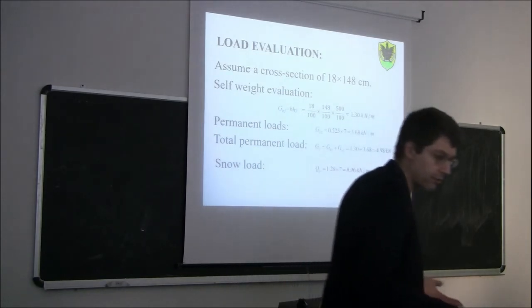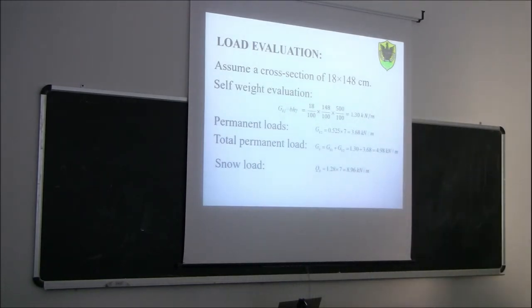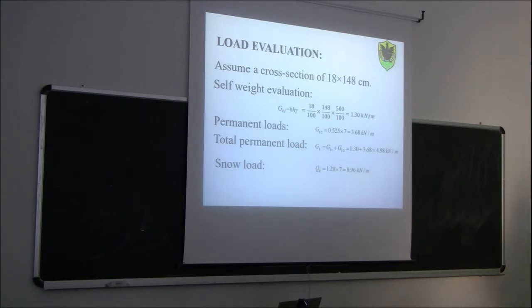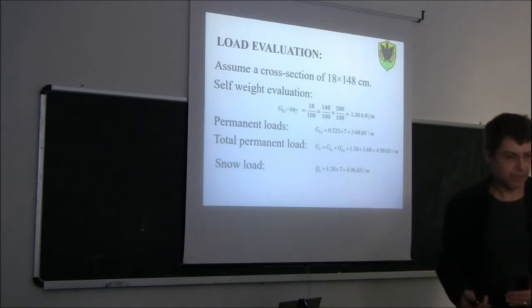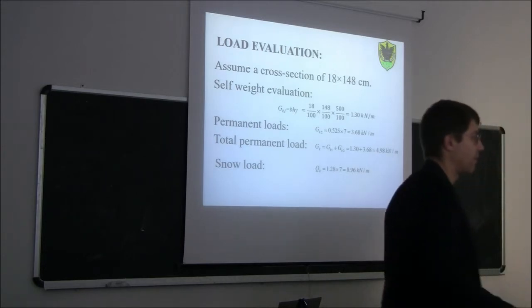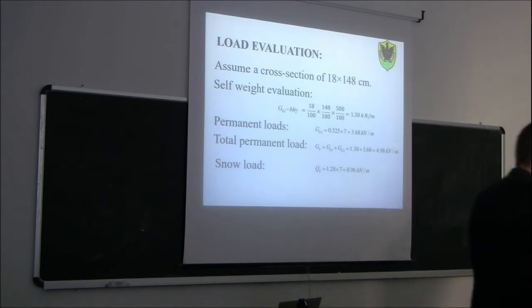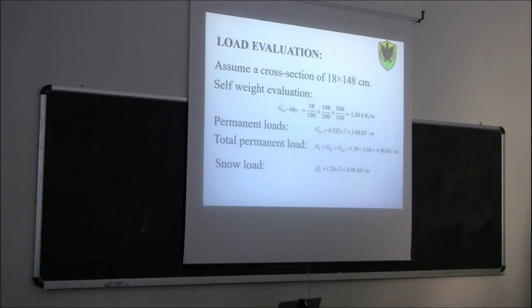Let's start from the live load. What was the live load in your design, your reinforced concrete design? Yes, which number do you have? 2. Exactly. So this was 2 kN per square meter. Of course, it is not immediately comparable because the timber value is already multiplied by the tributary width, but in your case it was 2 kN per square meter. This was the live load. And what was the self-weight of your floor in kN per square meter, more or less? Do you remember?